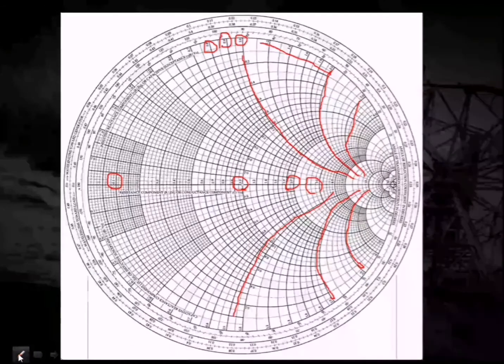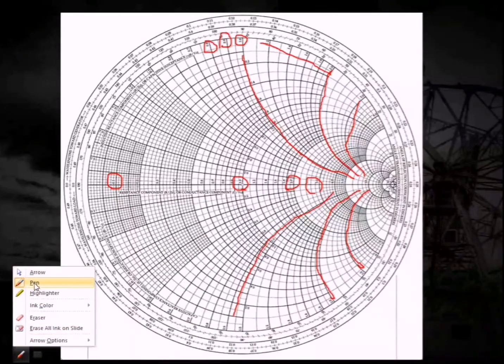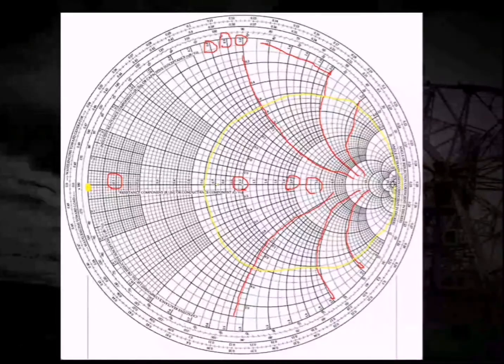And similarly, if I talk about the resistance circles, then let me change the color of the pen. Then you will find this circle. This is at 0.6, so this circle will move over here and it will pass through this point like this. So this will give us the value of the resistance circle. If I move towards a higher value of the resistance RL, my radius will start decreasing, and if I move to a lower value, my radius will increase. This value is for RL equal to 0, whereas this value is for RL equal to infinity.